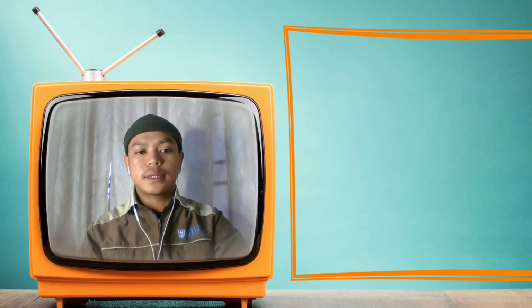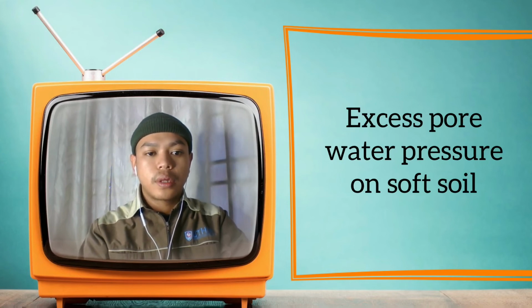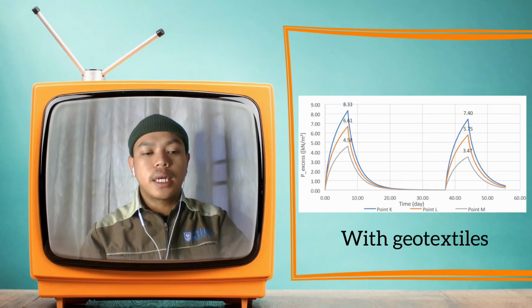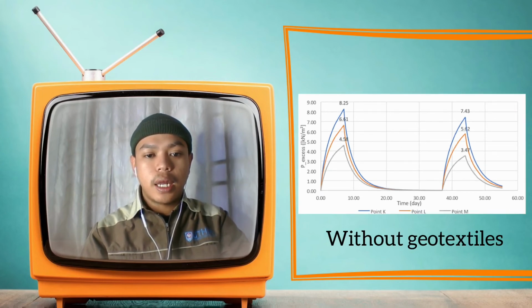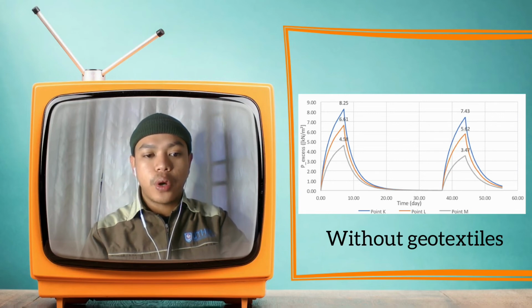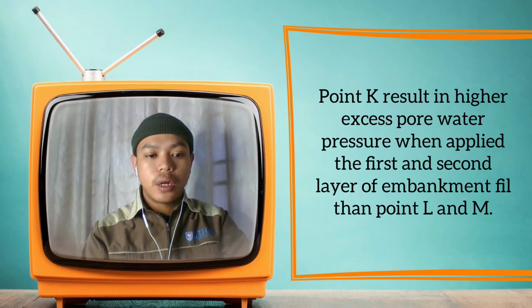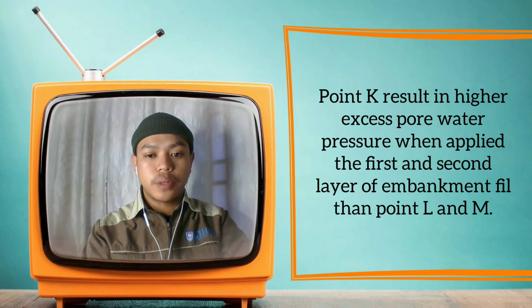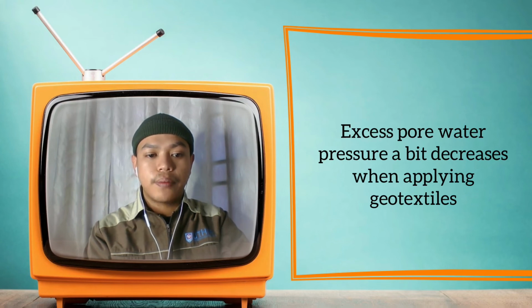The next result and discussion is about the excess pore water pressure on soft soil. Soft soil with and without geotextile under excess pore water pressure has also been simulated in Plaxis study, using 3 coordinates selected, which are points K, L, and M. In both results with and without geotextile, point K results in higher excess pore water pressure when the first and second layers of embankment fill are applied than points L and M. The result also indicates that the excess pore water pressure decreases a bit when applying geotextile.